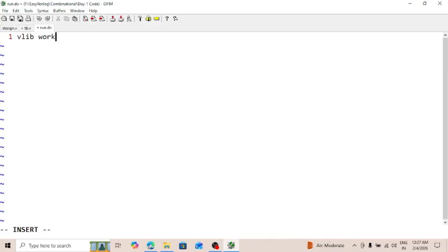After that vlog tb.v, the TestBench file name. After that vsim tb, the TestBench name, run -all. This is our scripting.